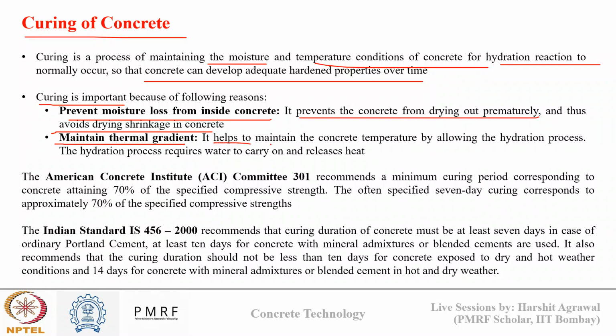So this helps in maintaining the concrete temperature, which allows the hydration process to continue. Different standards say different things about the curing period. The ACI standard says that the minimum curing period should be till the stage the concrete has achieved 70% of its compressive strength, and this is often related to 7-day curing.